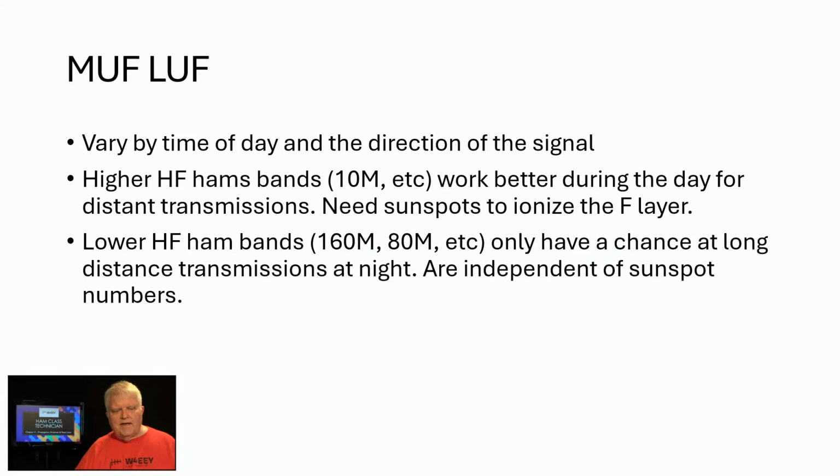They vary by the time of day and the direction of the signal. The higher HF bands will work better during the day because of the sunspots. The lower HF bands work at night because the D layer goes away. So some things to consider. I'm going to show you a propagation tool you can use to help you determine, if you want to work a station in England, what's the best time of day and the best band right now to actually be operating, to hear them and for them to hear you.